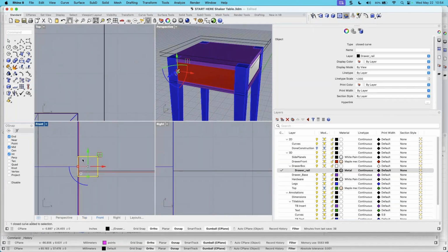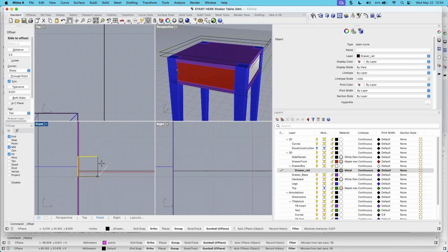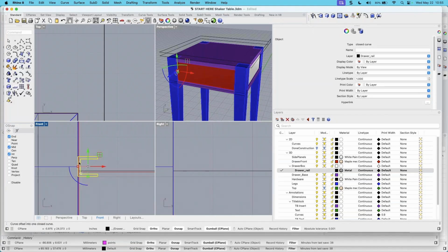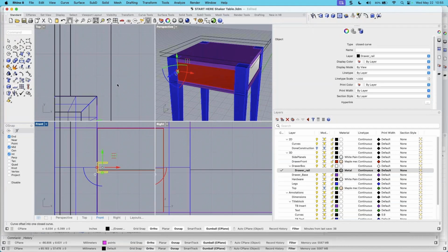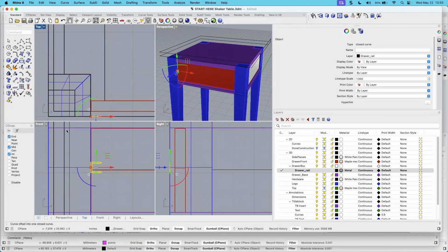So it will consist of a channel and a tube. So I'll take this and I'll explode it, and I'll pick on that curve. I want that to go away. I'll window these and I'll join them together. And then I'm going to offset on the inside by 0.06. So it's a real thin metal here. Okay, so that's our channel. That's the profile for our channel.